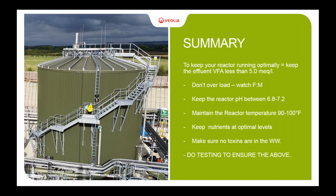Second, the two big things are pH and temperature. Most reactor upsets occur because the pH gets out of control or the temperature gets out of control. These are typically measured online, so you should potentially have some interlocks in your systems that prevent things from happening. And if you don't, you should make sure you're calibrating those instruments, because they're extremely important.